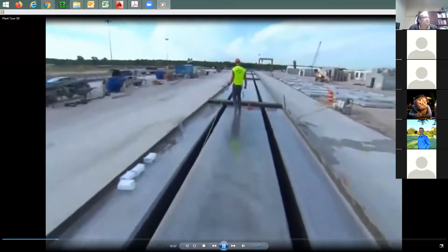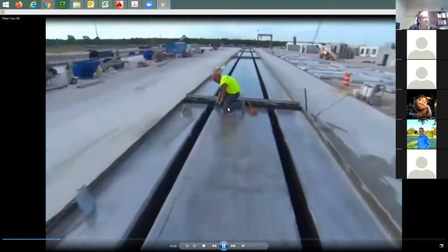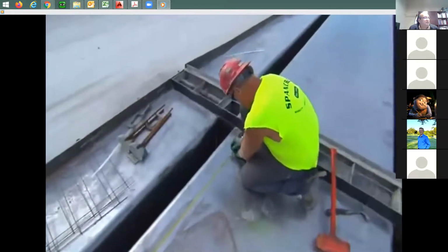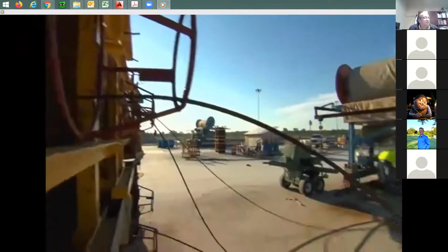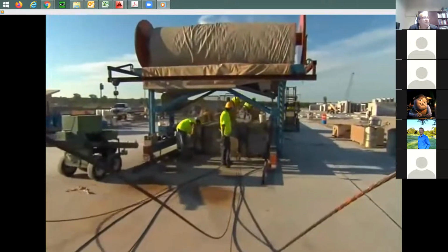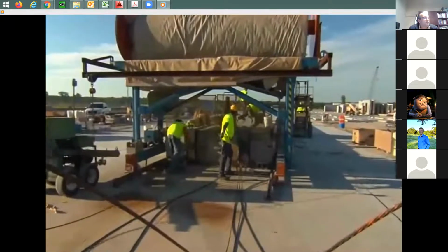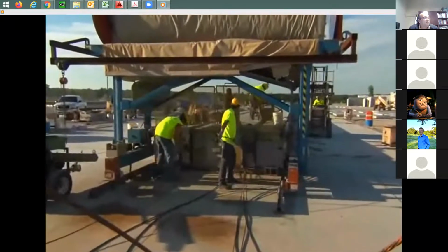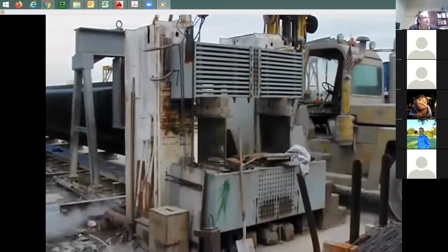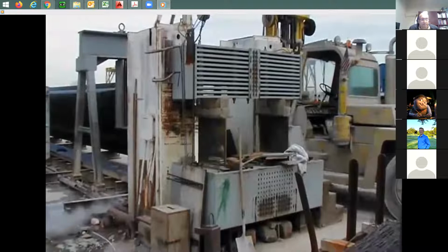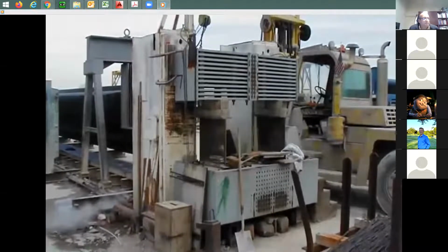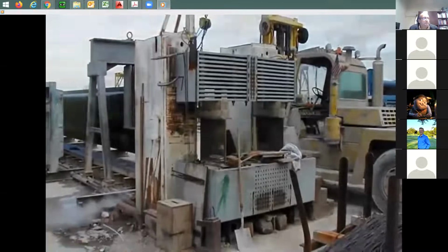This particular bed is set up for 5 double Ts, each about 60 feet long. The bed has a total length of 400 feet. This is a self-stressing form, where the form itself is designed to take the total pre-stress force in compression and also to handle the eccentricity of the strands. Sometimes the producer may use a form that is set between bulkheads that are built right into the ground. The pre-stressing force is then resisted entirely by the bulkheads and their foundations.